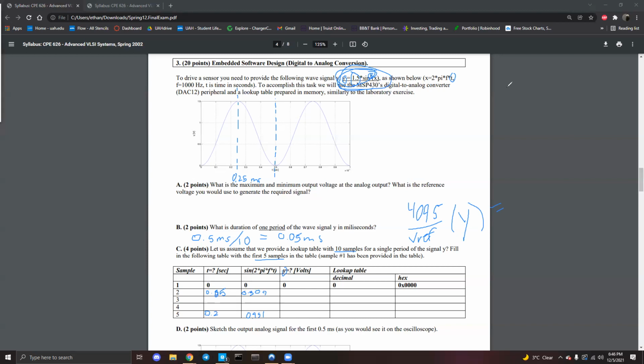But no, he's almost always given us, and particularly here, in all the instances, a DAC 12, it's a 12-bit DAC. But 4095 is the standard number. I don't think we've seen another one, maybe in a homework, but even then I think it was always 4095. But he could say like DAC 8 or something, in that case, just know that where the 4095 number comes from, it's just 2^n minus 1.